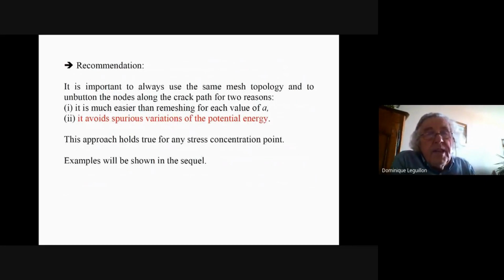Just one recommendation: if you try to implement the couple criterion using this approach, it's important to use the same mesh topology. You mustn't change the mesh in between the different steps of the computation. The first step, where you calculate the tensile stress, and the next step, where you release the nodes, concern the same topology of mesh.